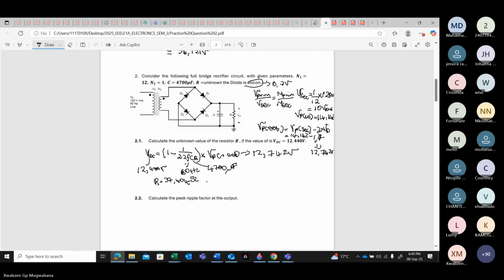Yes, sir. Okay. Then from there, we know that this is the calculated value. But now, because this is the practical circuit, we need to make sure that we take this value and convert it to E12 series. Remember, I told you that from chapter 2, everything we converted to E12 series. Now, in E12 series, what is going to be this one?